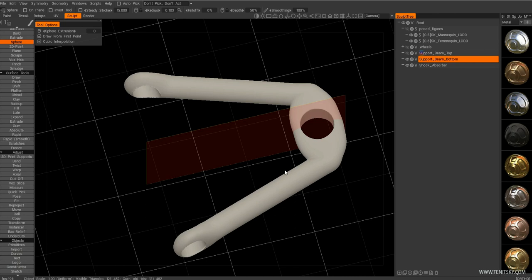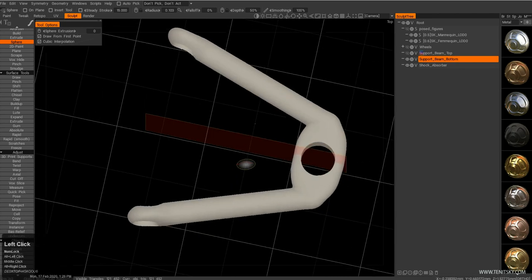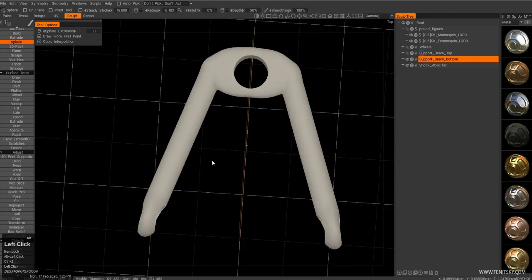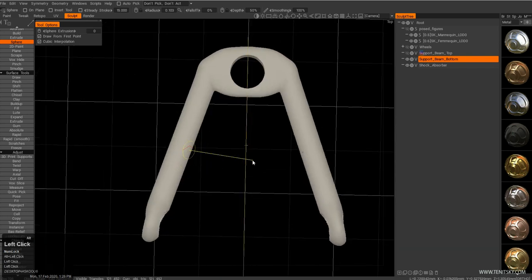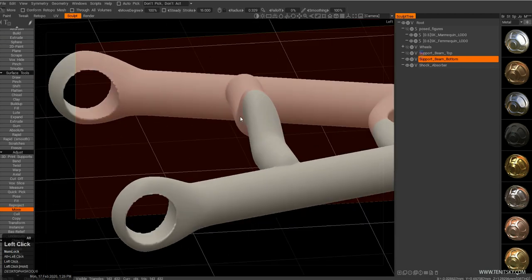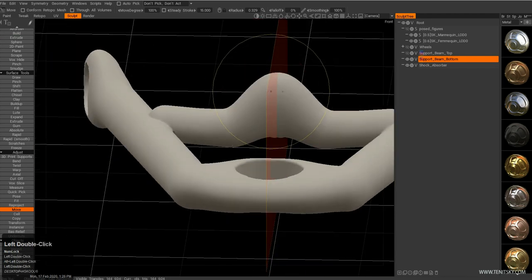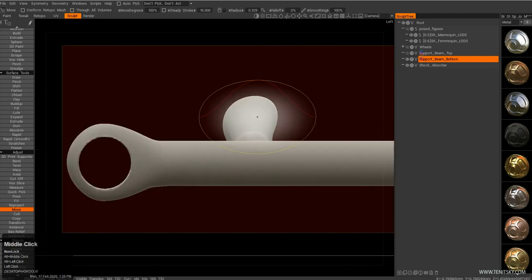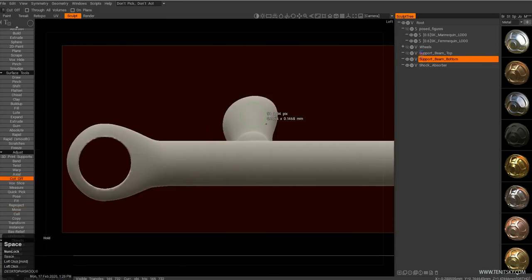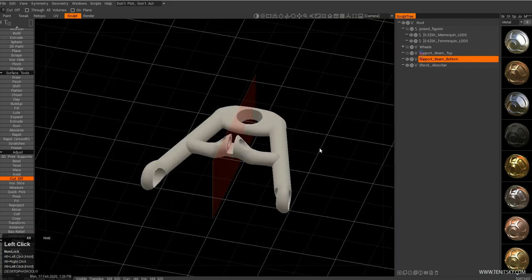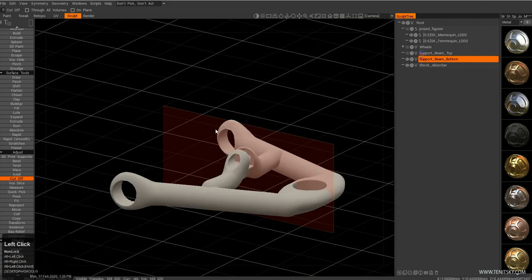To create a shock absorber, I need to link it to this bottom support beam. So I'll draw this part and just use the move tool to make it bigger, so I can then cut through a few parts. Then I'll just use the cut off tool here, cut off tool here for our link connection, since it will rotate in one axis over here.